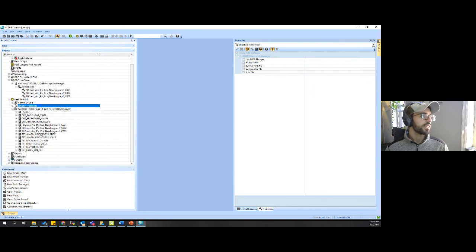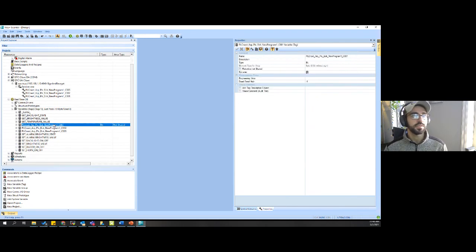I know what you're saying because OPC DA was a little different. There you go. They are automatically sorted from the OPC UA client into your real-time databases. So if you see over here, they already show up down here, right? I'm clicking through it, and it shows as a bit type, which means it's a Boolean, right? Does that answer your question? Please let me know. Thanks, Tom.